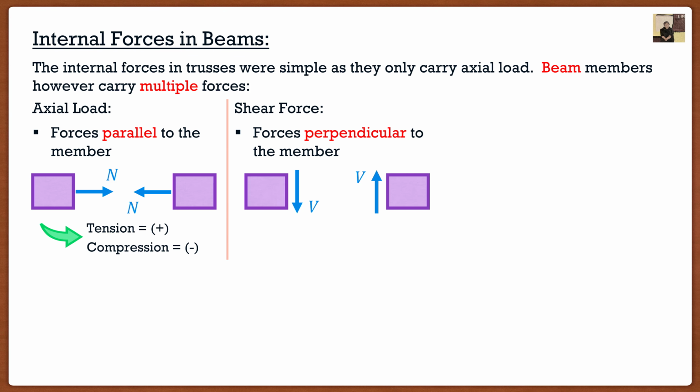And the reason why this is so deadly is because it happens in a matter of seconds. One of the things we do as engineers is we want to make sure not only is our building safe, but if somehow it were to fail, we want to make sure that it gives the occupants inside enough time to get out. So for instance, if my roof were to collapse right now, I would design it in such a way that the roof would start to sag a lot. Because then I would look up and say, oh, the roof's coming down, I better get out. Shear doesn't give that warning time. If my building were to fail in shear, that roof would just break in half. I'd be dead right now. So shear is a killer force, but it's one of the most important ones when we design.